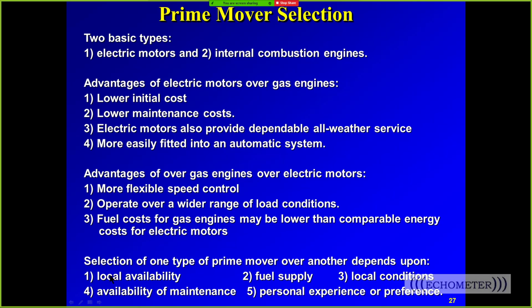So which one do you use? Well, you use what's available locally. If the well doesn't make any gas, you can't use a gas engine. If you can't set power poles because it's in rock, hopefully you use gas, not electric. If you don't want to have a mechanic, you don't use a gas engine. If you don't want to have an electrician, you don't use electric motors. And maybe your boss comes in one day in the office, takes his hard hat off and throws it across the room and says, "We'll never use one of those blankety blank." He might say electric motors or gas engines one day. It's personal preference sometimes.